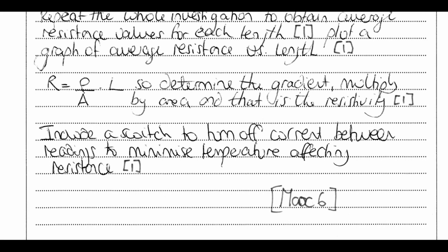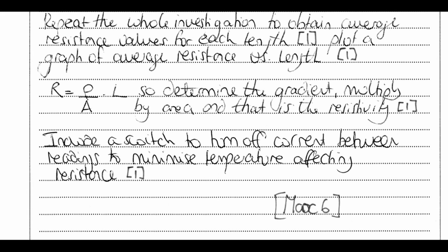So an important thing here is resistivity can change with temperature, so during this experiment you're going to need to make sure you keep temperature change minimized. So that's why you stick a switch in your circuit, turn off your current between readings. That's going to minimize that effect. You might also put an external resistor in your circuit to have the same effect there, keeping current low. Okay, so that's your experimental method.